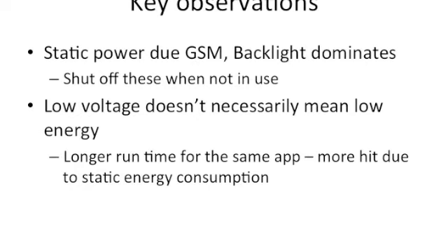During that time, components which are dissipating static power, maybe your GSM modem is on, your backlight is on, are going to consume more energy because the application is taking more time to finish. So that is why time comes into the picture as far as optimizing energy goes.